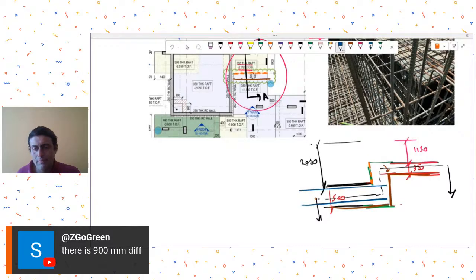You may leave it over here, because generally we are assuming that the designer, at this fold, because the fold is almost a 90 degree difference, must have assumed an edge release over here. Edge release means they are not relying on the continuity effect at this location, because you cannot have continuity with a 90 degree difference. So what we can do therefore is, top bar you can leave it here.